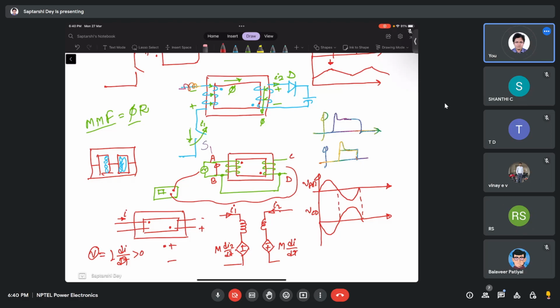You can simply remember it like that in a DC-DC converter. If you have multiple windings and you ever get confused, simply follow this way of drawing the transformer, putting the dots as per your drawing, then draw the whole complete circuit, then analyze the flux and analyze the circuit.